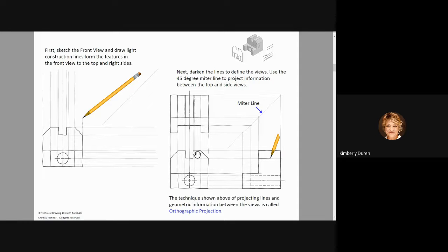Then I have this right here. I have this inclined plane. Now that is absolutely on the same plane as the bottom of this notch. So I'm going to put the visible line over here for that inclined plane, and no hidden line. You don't step that down. It needs to be absolutely horizontally in alignment with this. So you just draw one line. Visible line overrides hidden line overrides center lines. Visible lines override everything. So I'm going to put that for this corner right here.